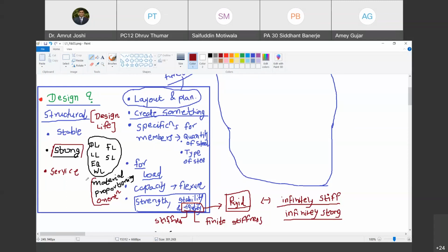Every equipment that the hospital has, for example, you can have a brain scanner, CT scanner, it comes with the prescribed limit of vibrations that it can sustain. So you have to design a building in such a way that the floor vibrations do not exceed that threshold. So therefore serviceability is contextual. Do you agree with me? Yes, sir. Okay, now let me give you another example.